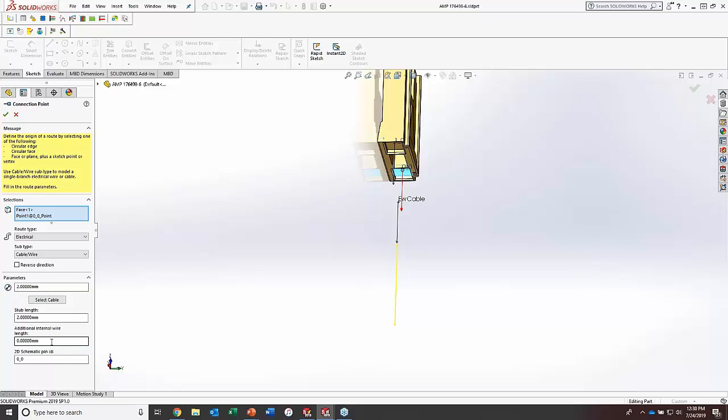So I do have a question here from one of the users. Just to confirm, if I have a dumb model, I can make the electrical connections in 3D electric. For example, the servo drive, then I would link the model to the schematic. Yes, you can link it, but then you probably are going to want to still walk it through that electrical wizard to make sure that you have walked through the connections to add those there as well.